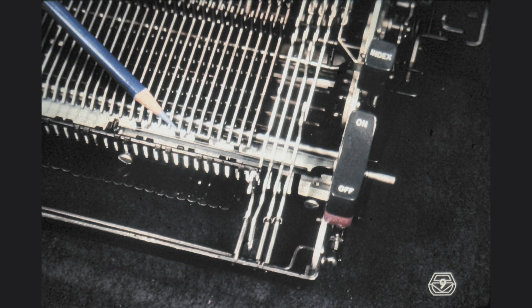This view shows the low-velocity vane located in front of the interposers. For every character with a small printing surface, there is one of these low-velocity selector lugs on the low-velocity vane. Forward motion of the corresponding character interposer will rotate the low-velocity vane top toward the front.